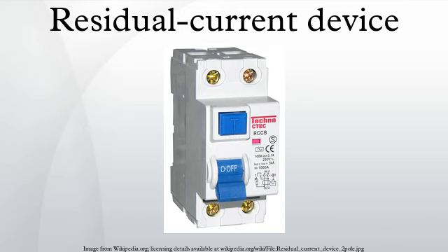Combined with overcurrent devices, residual current and overcurrent protection may be combined in one device for installation into the service panel. This device is known as a GFCI breaker in the USA and Canada, and as an RCBO in Europe. In the US, RCBOs are more expensive than RCD outlets. As well as requiring both line and neutral input and output, many GFCI RCBO devices require a functional earth connection. This serves to provide both the commons and to reliably operate the device if the input side neutral connection is lost but live and earth remain.